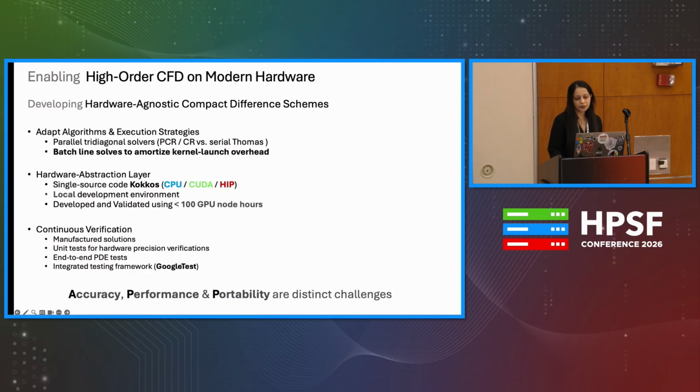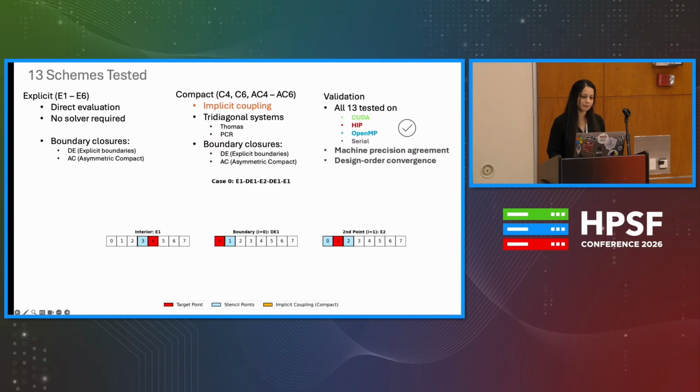And the third is continuous verification. We use manufactured solutions with known analytic answers, unit tests that verify hardware precision, and end-to-end PDE tests, and everything is integrated with Google Test for automatic regression detection.